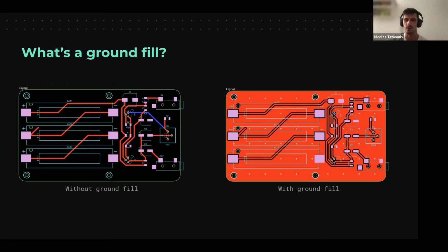And you also notice that it has a range of vias in a regular pattern. That's called via stitching. So basically, it connects the different ground planes in different layers together, so that there's kind of one continuous connection to ground.